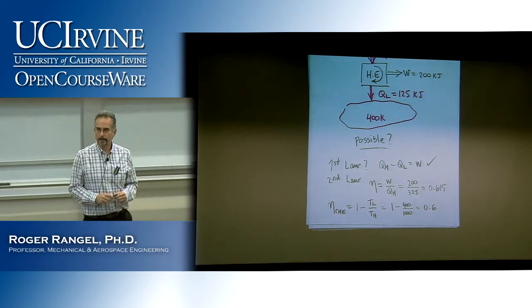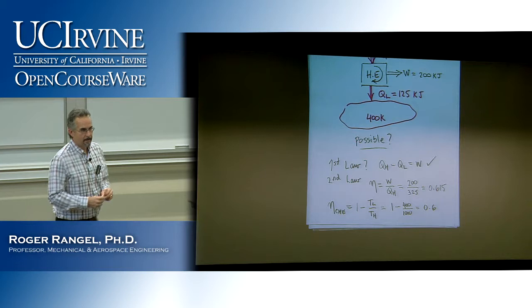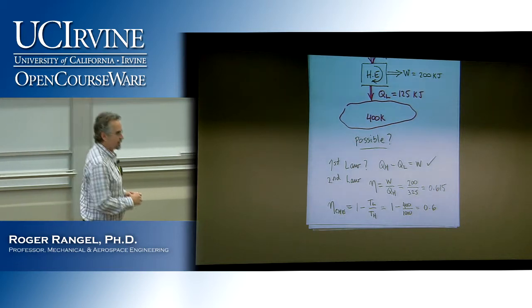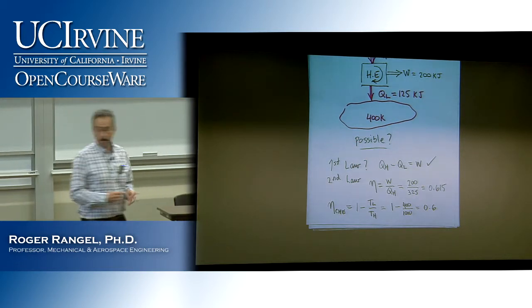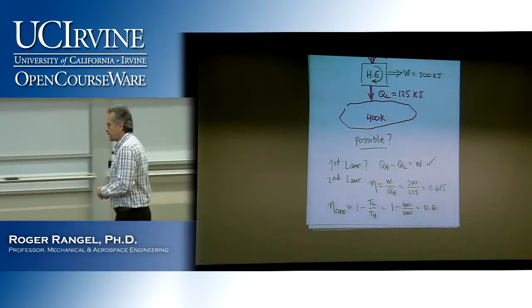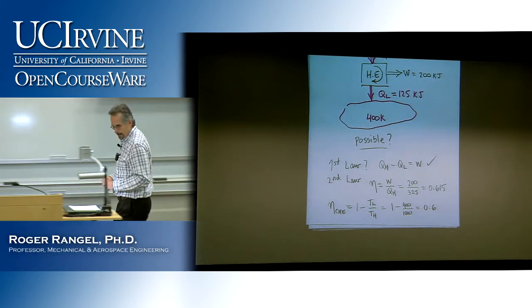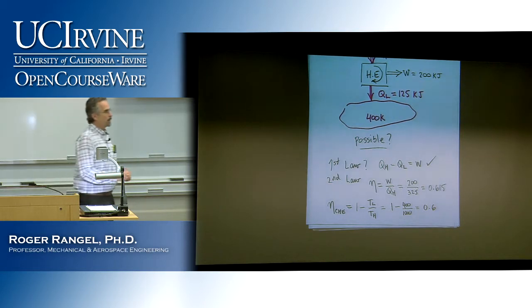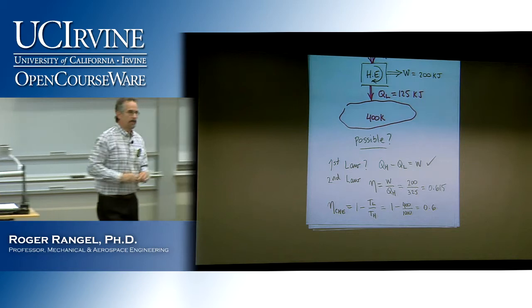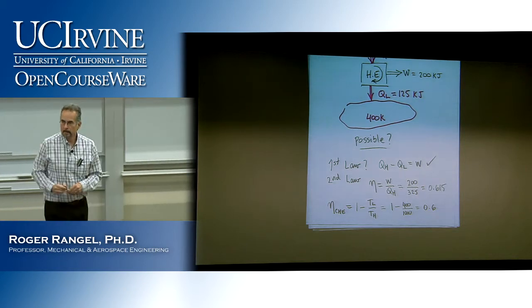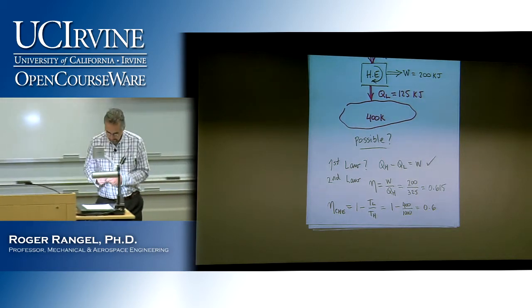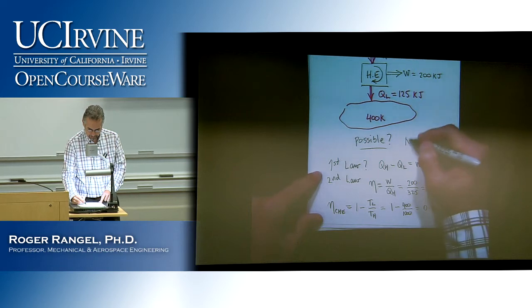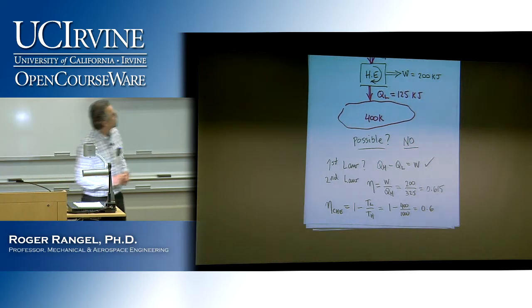So now we can answer the question. Is this engine possible? No. The answer is no, because this heat engine, as described, has an efficiency that is higher than a Carnot heat engine operating between those two temperatures, and that's impossible. So the answer then is no. It's not possible.